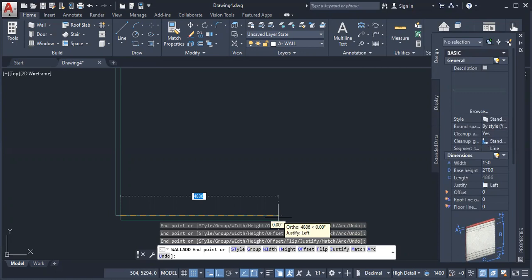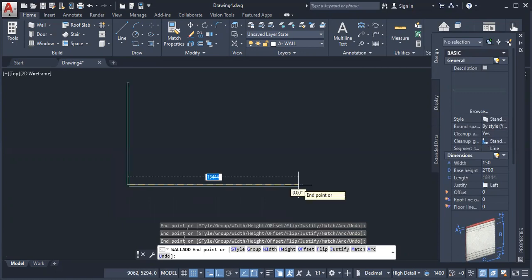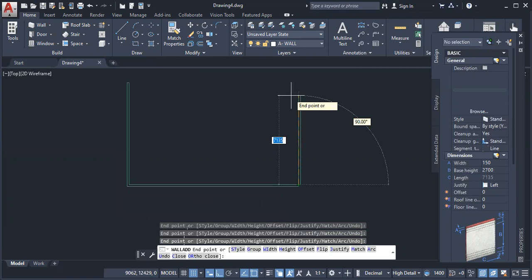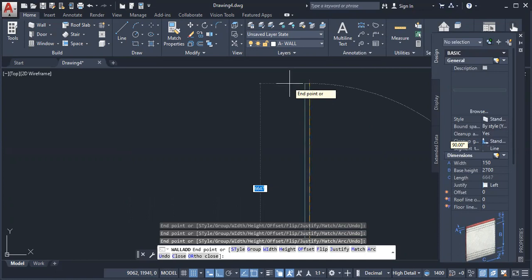All right. Very important. As I click here, then I move up. Please note that control can be used also to flip. Look, I press control once. Look what happened. The justification is now to the right. So again, one more time, so that it's now to the left. As you click the control key, it flips justification to the right or to the left.